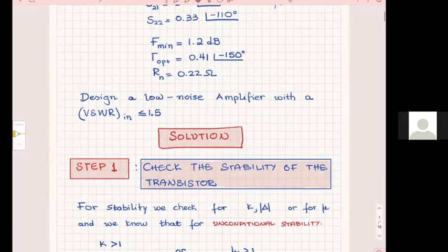Now, what is new, as we said last time in this transistor, is that they have told us that on the front end, you may come from a filter, we said, all right? Normally you will come from a filter to go to an LNA. And you don't want to have very high reflection because that is gonna push your incoming frequency back. Your incoming power is gonna be reflected, a good portion of it, and then what is gonna go through the low noise amplifier is gonna be even lower. So it compromises really your optimum design. So you have to have a low VSWR at the input port as it shows there.